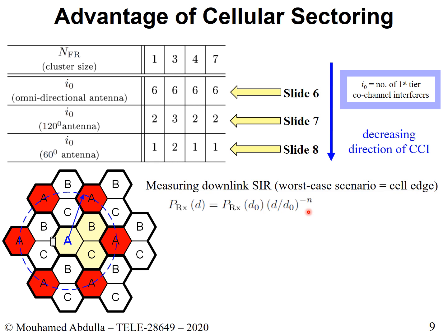So we will just consider the middle point between 3 and 5, and then we generally will use n equals 4. So here you would simply enter minus 4, and that will take care of this part here. Okay, so this is the equation for the channel loss when we work in mobile communication. This is an important equation. It will show up in other places.